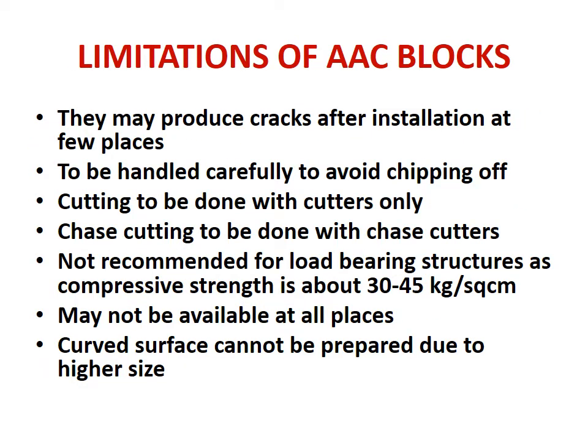Let us talk about some of the limitations of AAC blocks. They may produce cracks, particularly at some places after installation. Then they are to be handled carefully to avoid chipping off, not like bricks. Cutting is to be done with cutters only, whether cutting of the blocks or cutting of the chases, etc. Not recommended for load bearing structure as their compressive strength is low, about 30 to 45 kg per square centimeter, and they may not be available at all places.